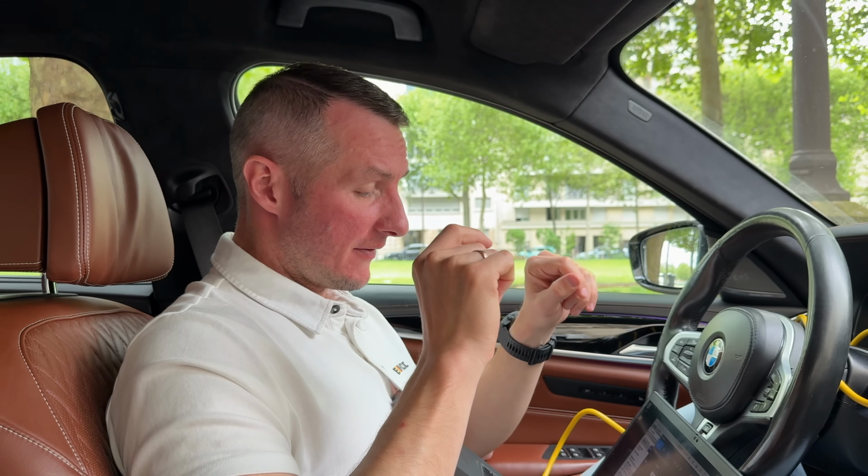Because whenever whatever value goes outside of the range, the ECU automatically registers the error. It's absolutely okay behavior. But if the error is repeated consistently over a short period of time, it means the error is presently physically present. For example, one of my sensors has either a wiring problem or the sensor itself is not working. If it was a wiring problem, the error would be appearing way more often.